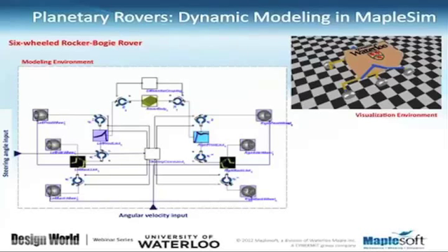These 2 are connected to the steering block here. That steering block is controlled by the input that you see from the left-hand side of the model. The other component that we obviously need to add is to be able to drive the car, the rover. And that is based on assuming that the front and the back wheel of the rover are the driving wheels. And these 2 are connected to the other input from the bottom side, and we are assuming that we have a position or velocity driver in this case.